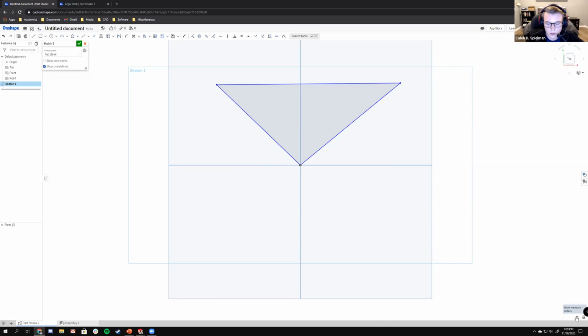And then we're going to evaluate. So evaluating in Onshape is a bit strange. So basically you'll just click two entities. It could be pretty much any entity, as long as it can actually compute values between them. So I'll pick this point and this point. Of course, I'll show you how to do this specifically later when you are able to use Onshape after we register for it. In the bottom right here is a measuring icon, and I can see the values that it gives me.